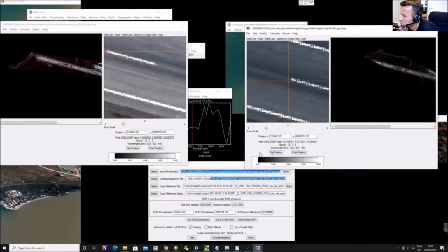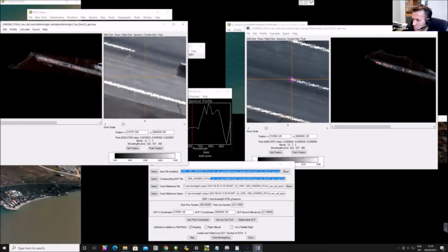You do have installations, of course, with, for example, a stabilized platform, where you have movement of the camera and IMU relative to the GPS antenna. But then you need to take that into consideration in the post-processing of the navigation data, which Agnar talked about yesterday. For drone systems, as I also mentioned yesterday, you have the possibility to correct for that in real time by having dual IMU.